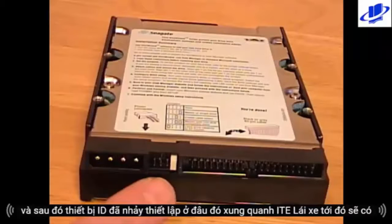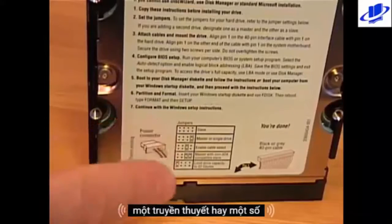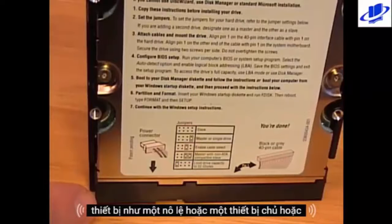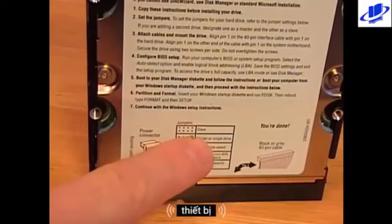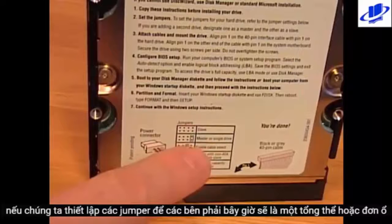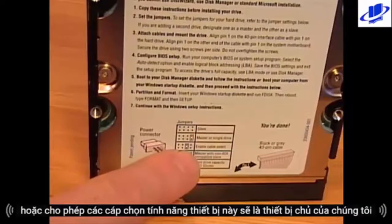And then our IDE device has jumper settings. Somewhere on the IDE drive there will be a legend or some indicators to indicate which jumper setting will specify the device as a slave or a master device or a cable select device. In this case, if we remove all jumpers, that would be a slave device. If we set the jumper to the far right, that would be a master or single drive. Or if we set it on the third jumper, that will indicate or enable the cable select feature.